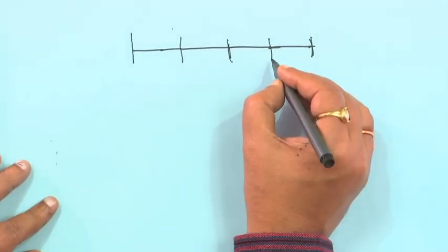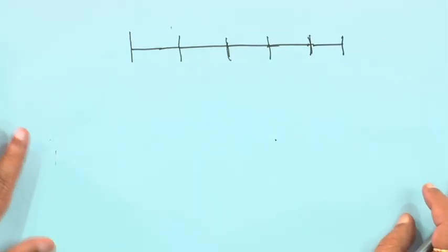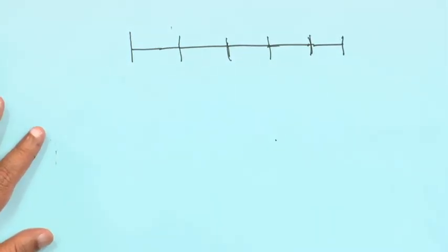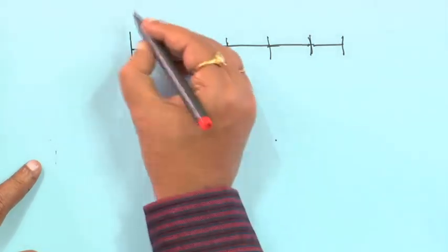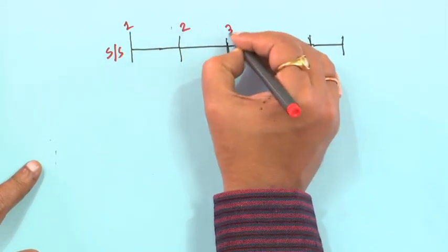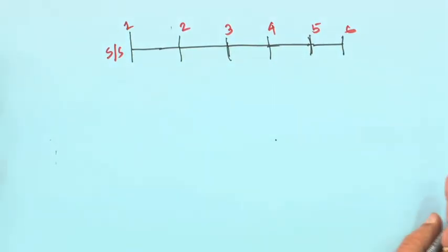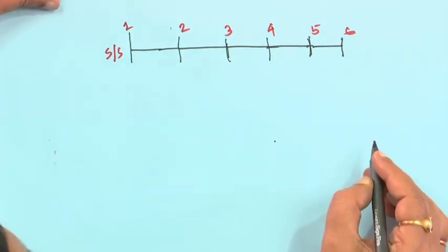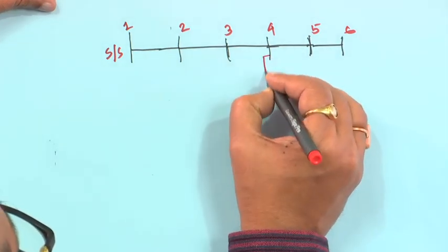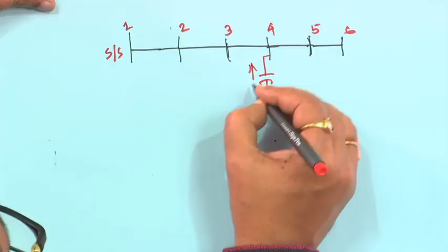Second thing: suppose you have a network, take a radial network only. First you understand all this; later you will find we have taken the simplest things from the classroom point of view. Suppose this is your substation, bus 2, bus 3, bus 4, bus 5, there are 6 buses. As our objective is the capacitor, suppose we have connected a capacitor at bus 4, so jQC is being injected.